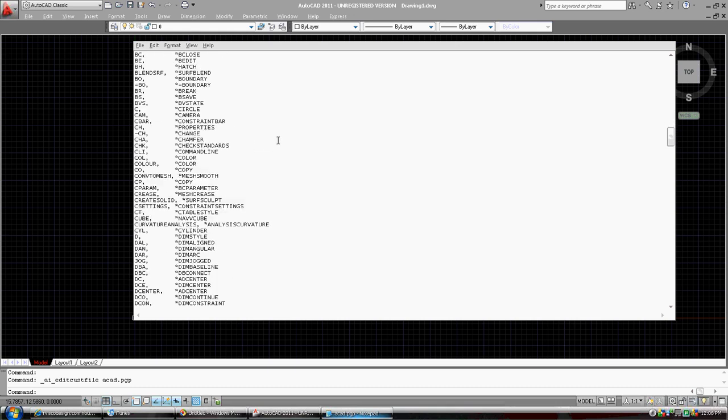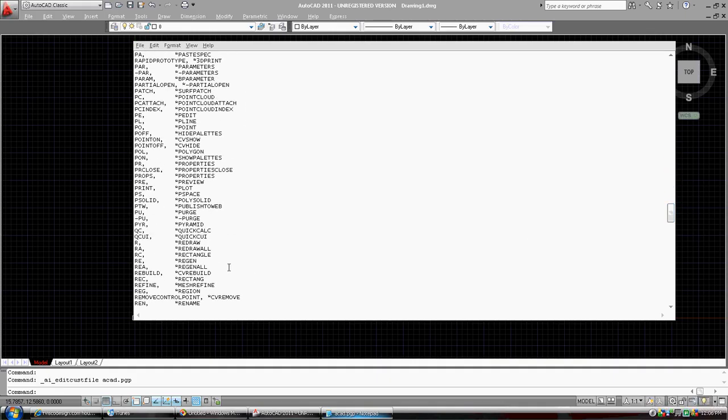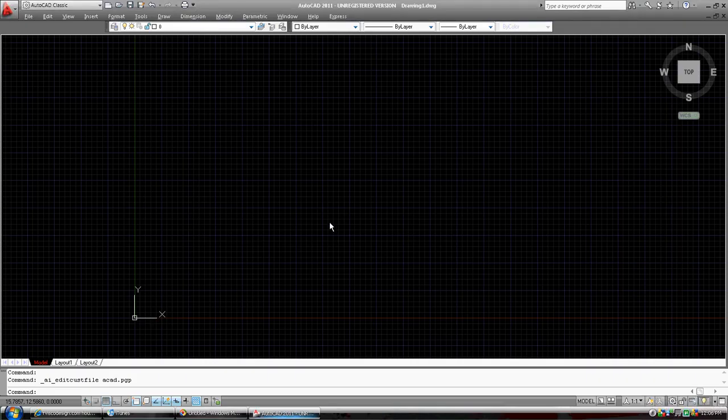Okay, so if you come down and get into the R's, and you go to rectangle, RC, now it won't be in yours, right? REC down here will be in yours for the rectangle command. Okay, we're going to change that. You can change that by just clicking in there, backspacing, and now RC will get you into the rectangle command. So anytime that we run into a problem where AutoCAD hasn't been set up for our abbreviations, we'll come in here and change it. Okay, you can click out of here. It should ask if you'd want to save, and you say yes.